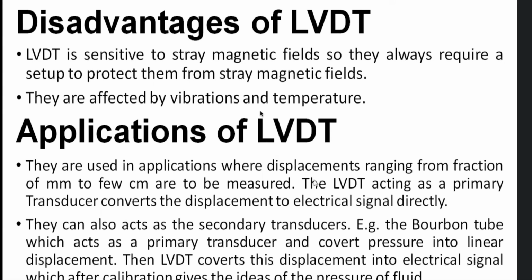Next, disadvantages of LVDT. LVDT is sensitive to stray magnetic fields, so they always require a setup to protect them from stray magnetic fields. They are also affected by variations in temperature. And next, let us discuss the applications of LVDT.